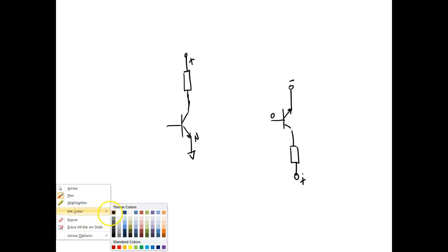Well, we control the current, but the rotor's got so much resistance. So what we're doing is we're controlling the magnetic field. But to control the magnetic field, we need current, but we can't have current without what? Voltage. So yeah, we control the speed with a voltage, even though the voltage is controlling a current, right?